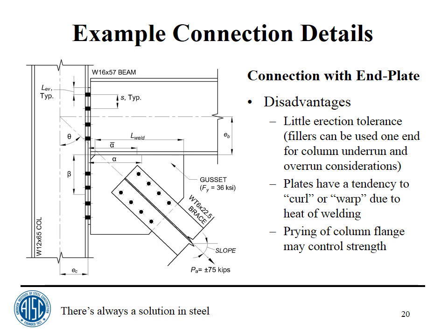And if you're talking about a heavy job with 14 by 500 odd columns, you're talking about 3 or 4 inch thick flanges. That's a lot of drilling. Okay. You can really avoid a lot of fabrication time by using shear plates in those cases, as you saw in the series of slides 2 weeks ago, and to some extent in the very first session, where I said